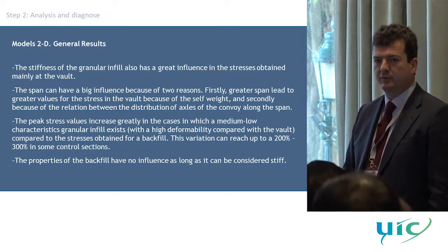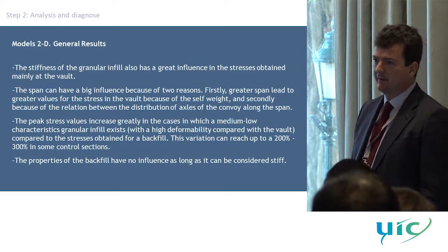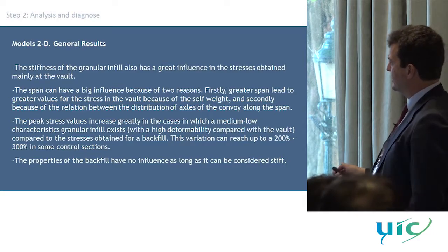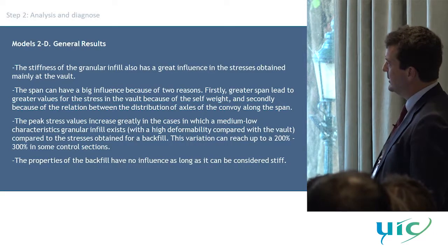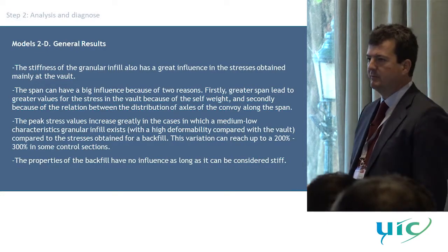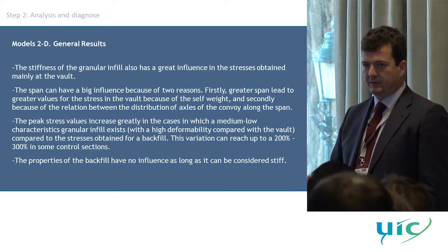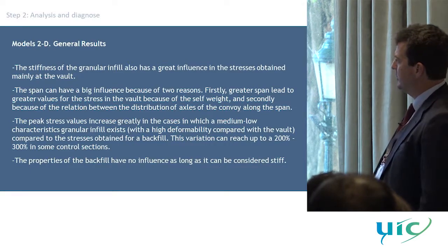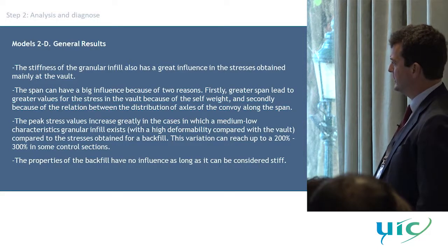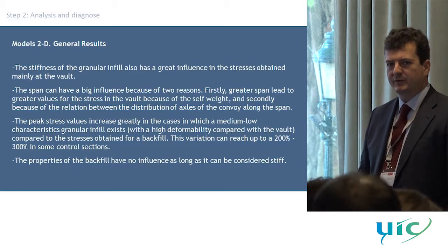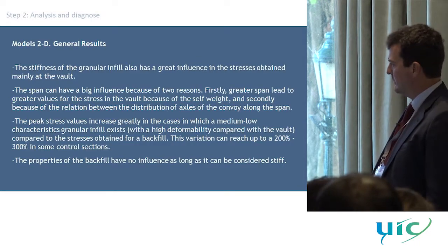But at the end of the morning, I will show you an example of how to retrofit a bridge by injecting the infills. The span, of course, has a big influence because of 2 reasons. Firstly, because greater span leads to greater values for the stress, and also in relation with the load patterns that we have in real trains. So sometimes 6-8 meters span can be more sensitive to real trains than 20 meters span. The peak stress increased greatly in the cases in which a medium-low characteristic granular infill exists with a high deformability compared with the vault. So that's what we were talking about. We have to take care about which is the structural meaning of the infill and which is the real role that it is playing in the overall mechanism.